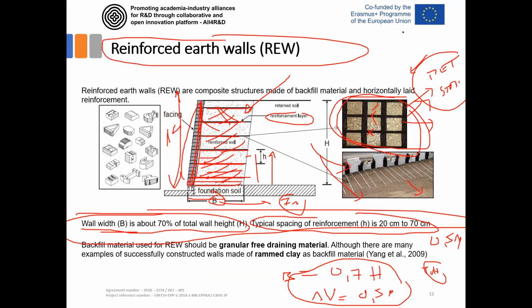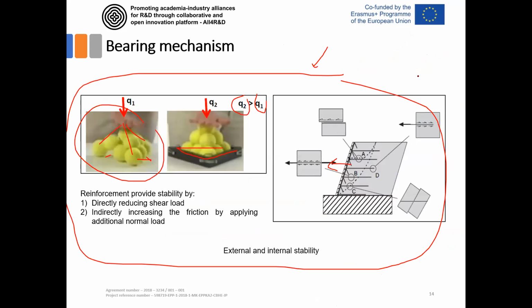So you do the excavation in one part. If this is the original ground, you do the excavation here and then you install the fill here. That's usually some crushed rock material, or it could also be gravel or sand, but that's not a material that we have so much of. We usually have crushed limestone or some other rock type.